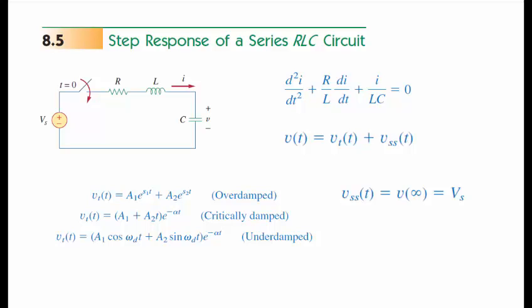Now we're going to look at the step response of the series RLC circuit, the series circuit, and then we'll look at the parallel circuit. So the step response means that we are going to apply a step to the circuit, which means basically that at some time t we apply this voltage. So at some time here, t equals 0, this voltage is applied, or the switch is closed, and the voltage is now in the circuit.